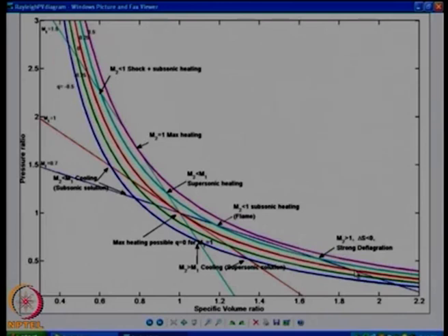This is corresponding to what we saw in our original BZT flows. No? We said somewhere that we have a strong sudden expansion wave, as in it's like an expansion shock. Okay? It becomes an expansion shock if I think about that particular case.